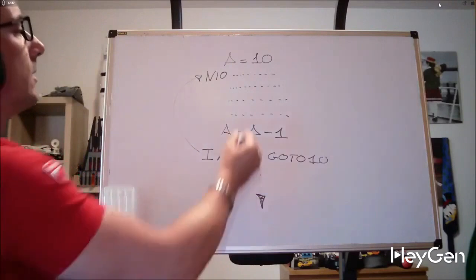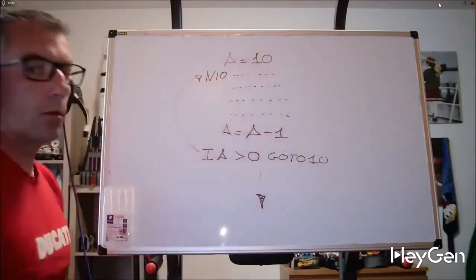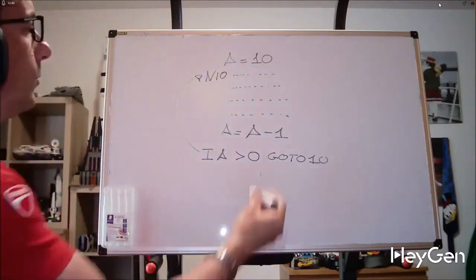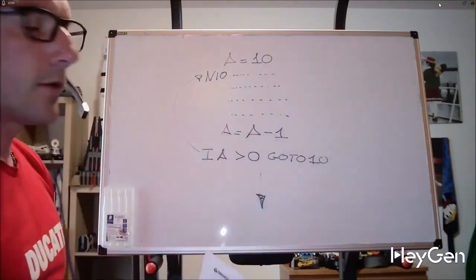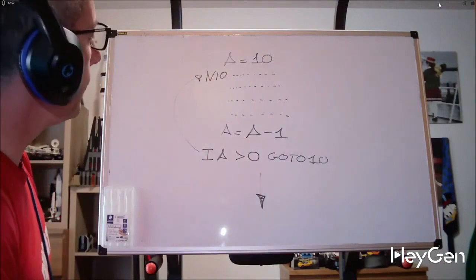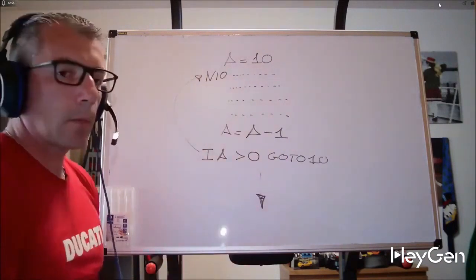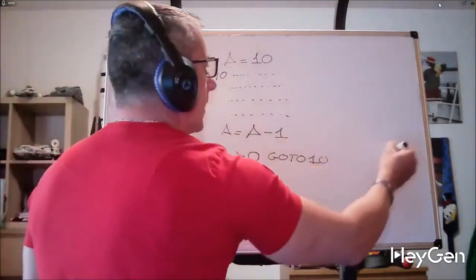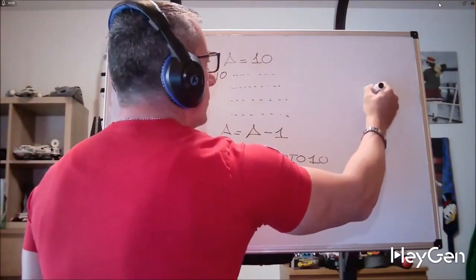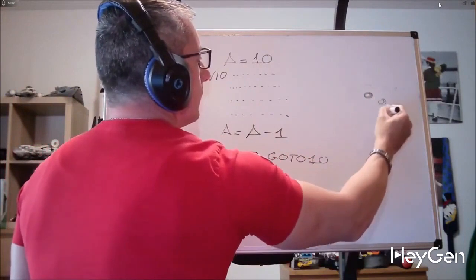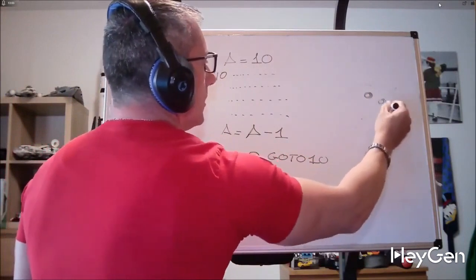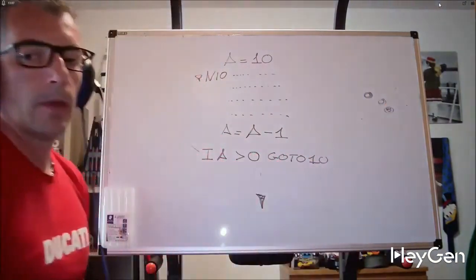You understand that this whole program, with a shift in origin, can be translated each time along the z-axis. So, I can have a program that makes a point with the power tool. I make a point, I drill a hole here, then I move my C and drill a hole here, move my C again, and drill another hole here.